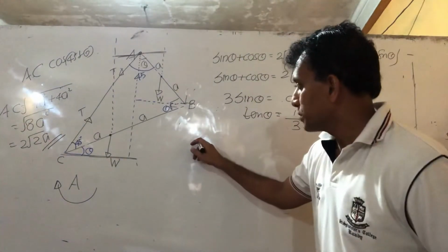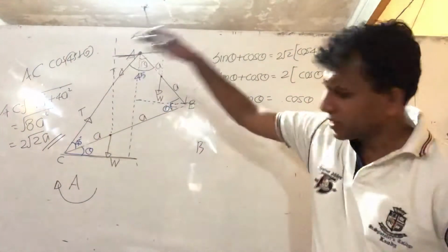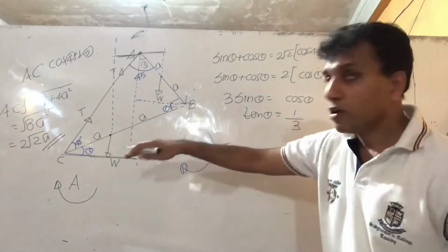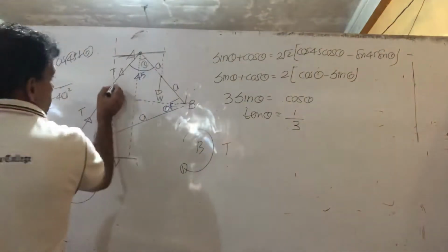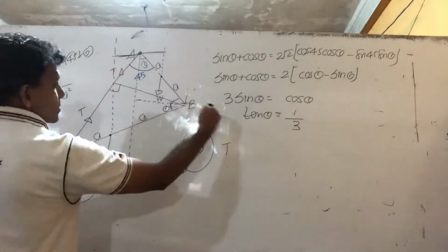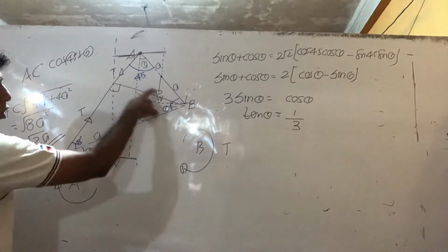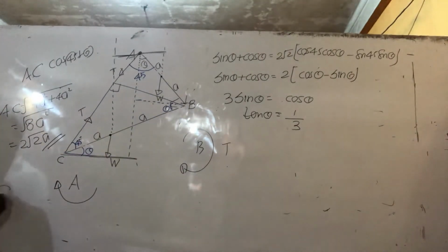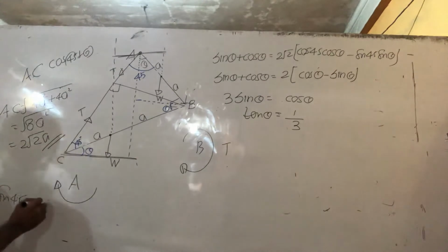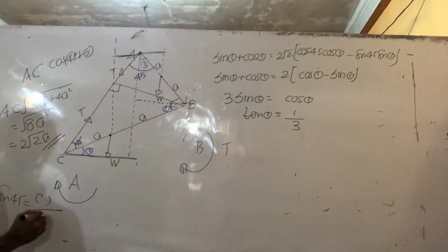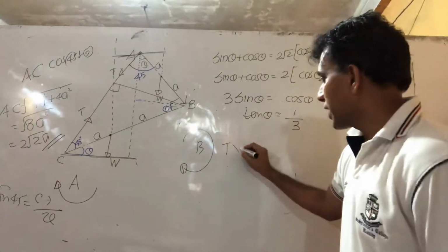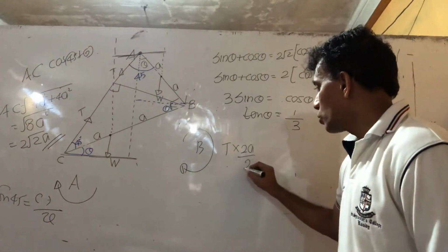Okay, so write that about B. Take a direction on that side. That side we mark, right? Force is T. What is the perpendicular distance like this? You know here 45, opposite unknown, hypotenuse is 2a. So what is that? Sin 45. If you apply sin 45, opposite over hypotenuse, 2a sin 45, that is 1 over root 2. Check that, 2a over root 2, right?